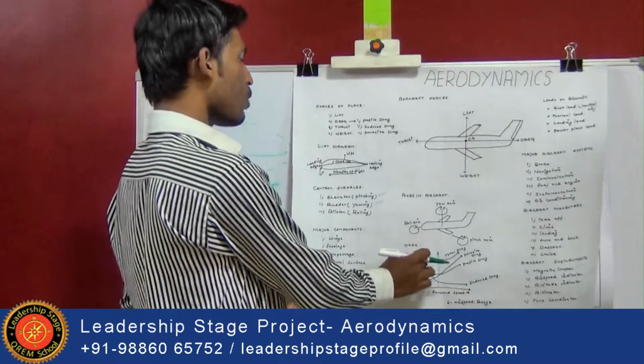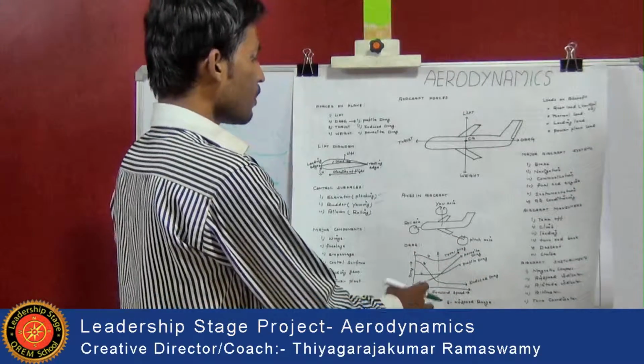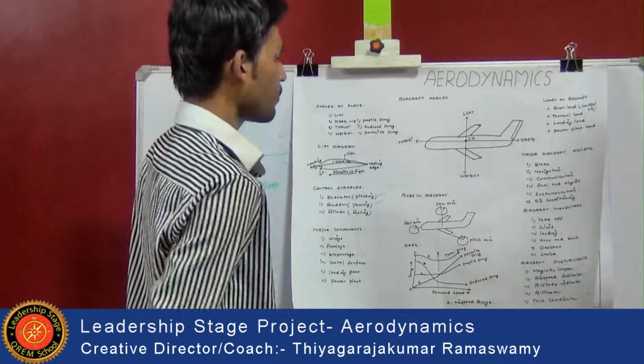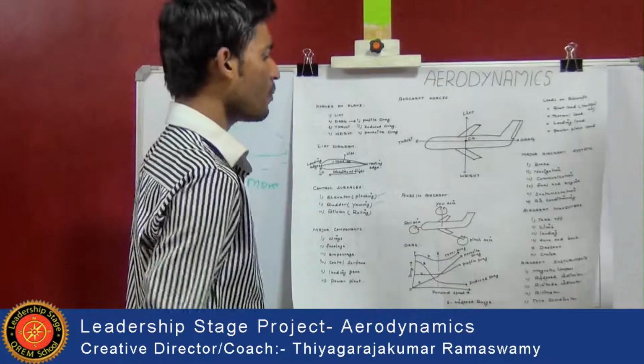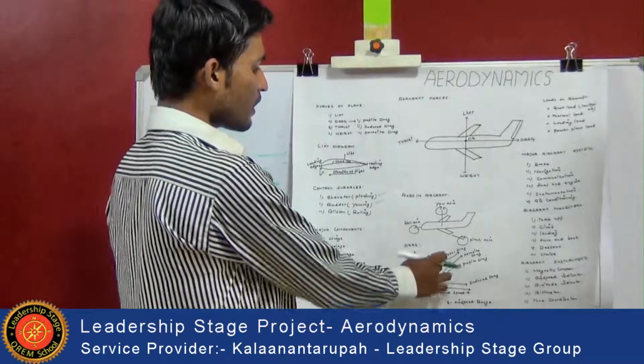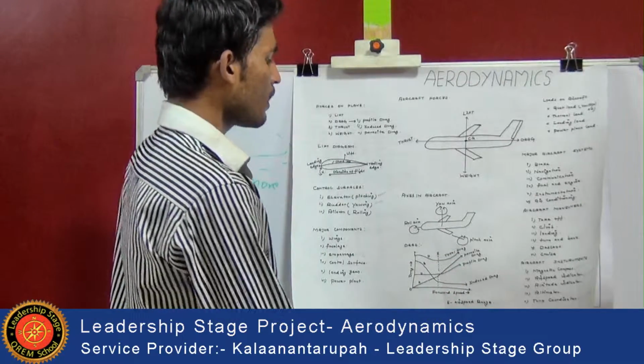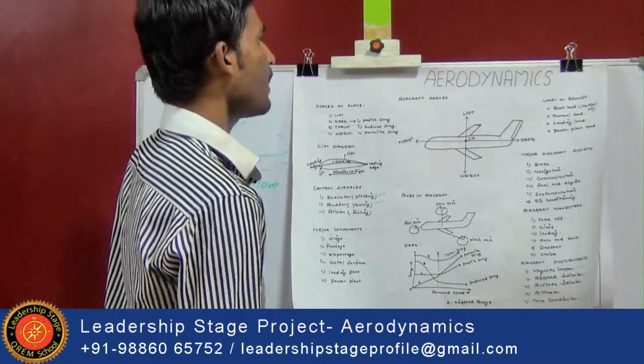And this is the total drag produced by the aircraft with respect to the forward speed. Here total drag is the sum of the profile drag, parasite drag, and induced drag. Here dotted line E shows the forward airspeed range of the aircraft.